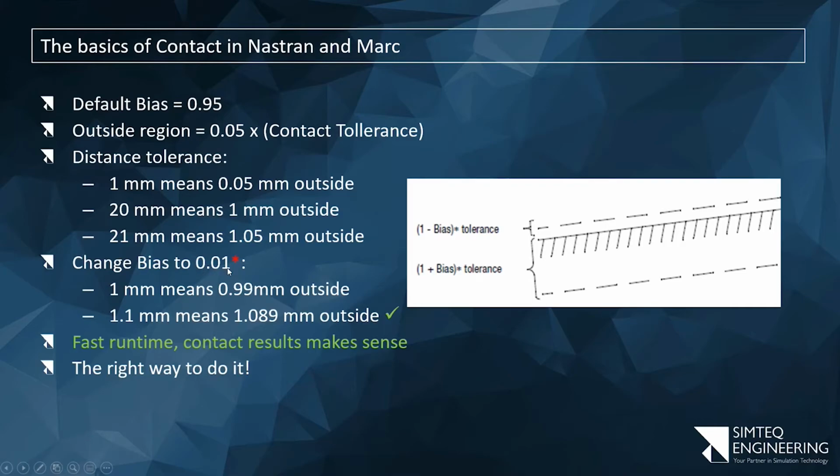Now, why did I specify 0.01 instead of 0? The problem is, I'm not certain whether it's still an issue, but initially in the Marc deck, if you write a value of 0, Marc interpreted it as use default. That was a convenient and elegant way, at least initially, but it complicates things later on. So if you make it just some small value, 0.01, 0.0001, doesn't matter. Anything that's not exactly 0 should work. Just be careful of using exactly 0 because you may get this kind of surprise where it's using the default, but you think it's 0.